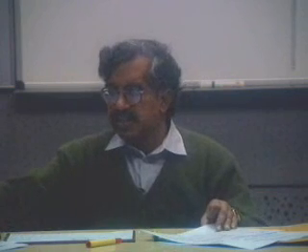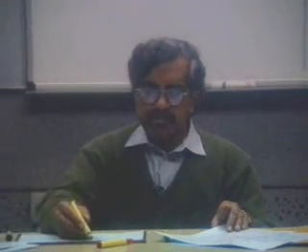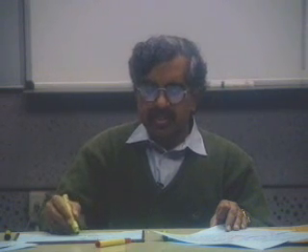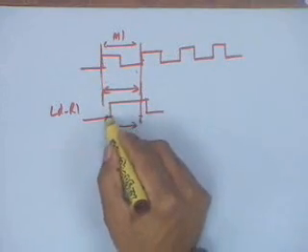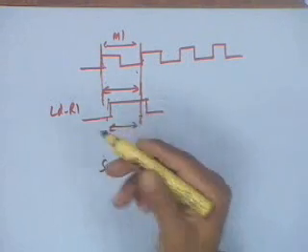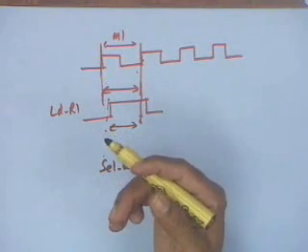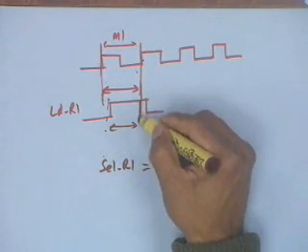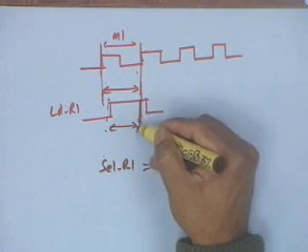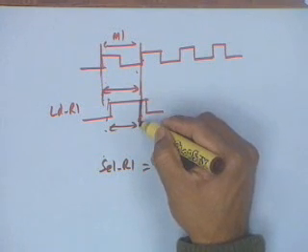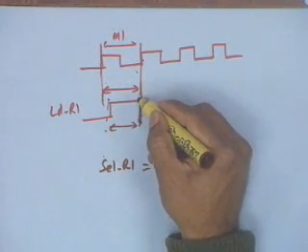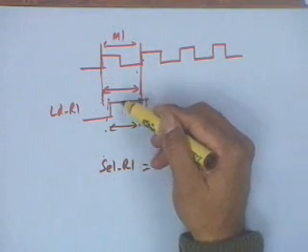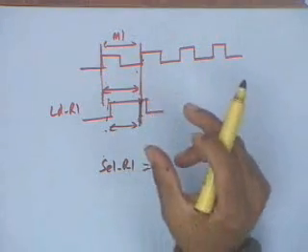Because whenever a particular microinstruction comes, if you say that the select for R1 is X, the select R1 will come and the multiplexer will immediately get that control input, and X will start flowing into the input of the register R1. But the register R1 will latch or load the value only at this edge. So it will have a stable input. All your setup time requirements will be taken care of by the clock period.